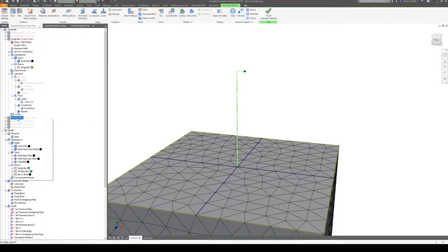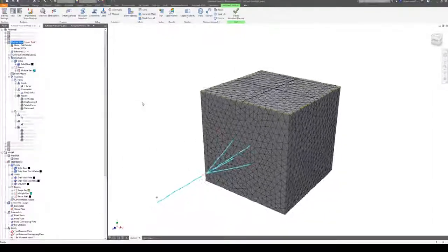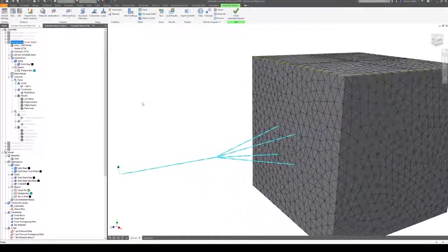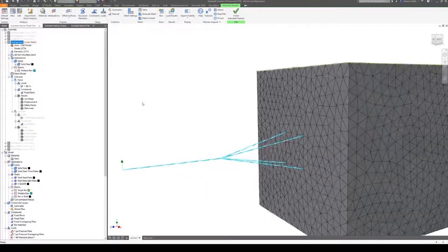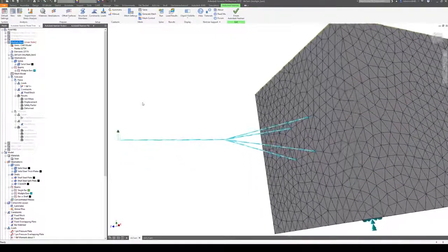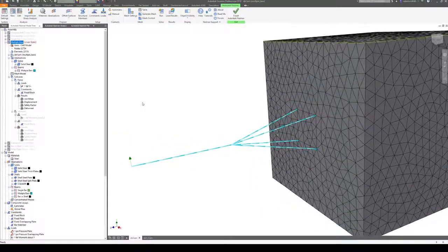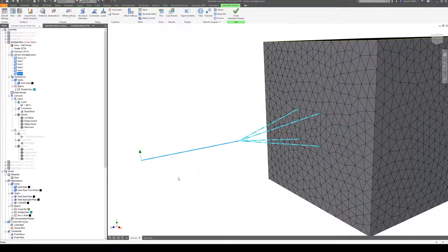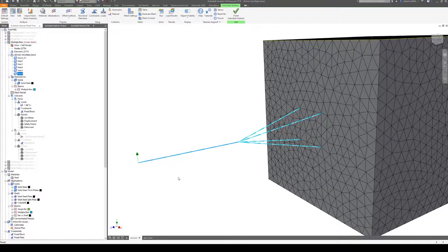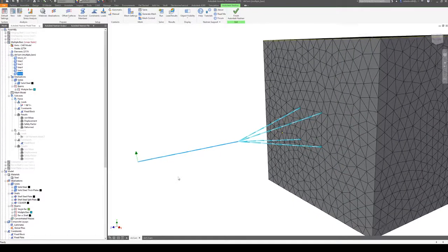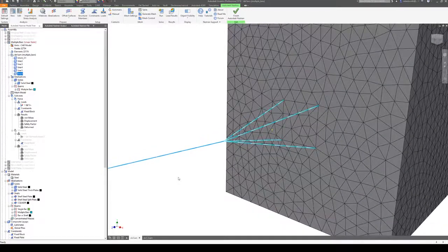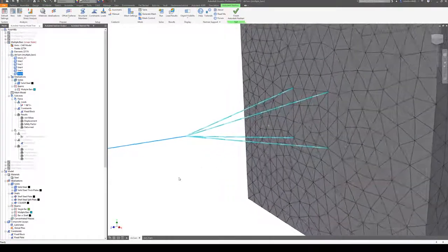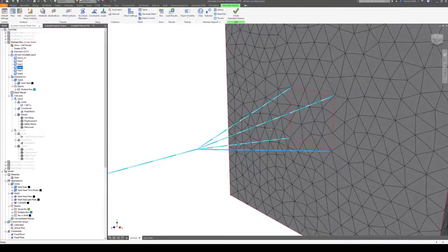So how do you deal with that? Okay, in this model here, the distances are a bit exaggerated to show you what's going on. We don't have to have such large spacing, but what we've got here is our bar structure, which would represent something physical in real life. But instead of connecting it to our solid structure at one node, we connect it to 4 other beam structures that reach out and connect to the solid at 4 nodes.